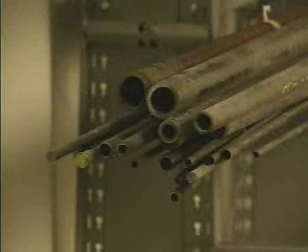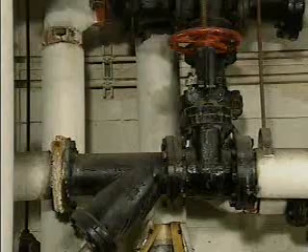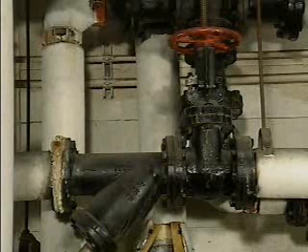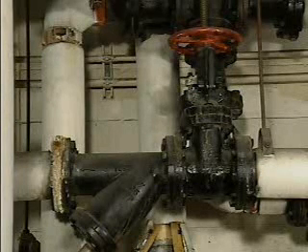Steel is metal that contains iron and carbon. The more carbon present, the stronger the steel. Carbon steel pipe is formed into different sizes while it is still red hot. Iron oxide forms on the exterior of the pipe as it cools, coating it black. Carbon steel pipe is extremely strong. For this reason, it is often used in high pressure and high temperature systems, such as hydraulic systems that push and lift heavy loads.